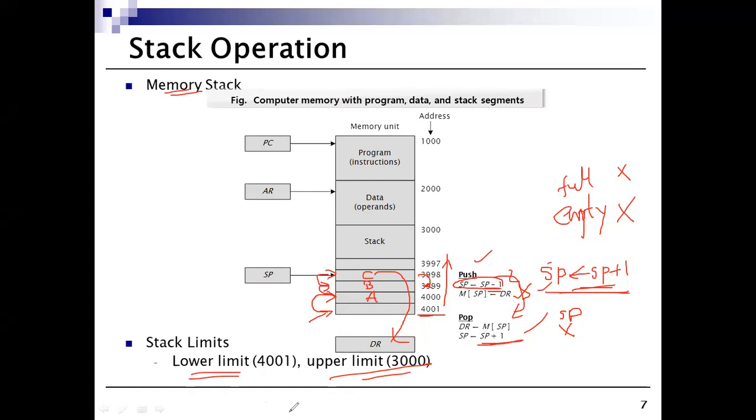Okay. So with respect to this, we have 4 different ways of organizing the stack. First updating the pointer, then loading the contents, or else you first load the contents and then update the pointer. If you do so, then the stack pointer will be pointing to an empty location every time, because the first operation is copying the contents.